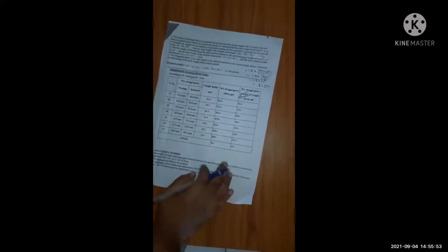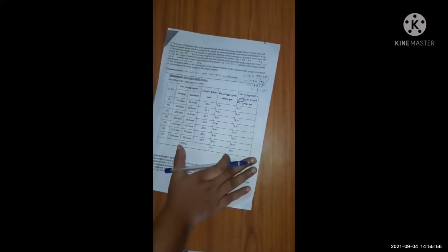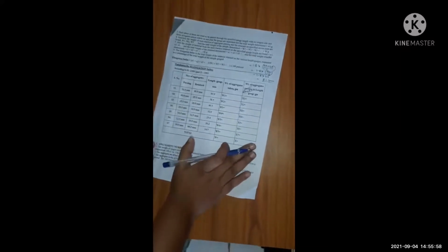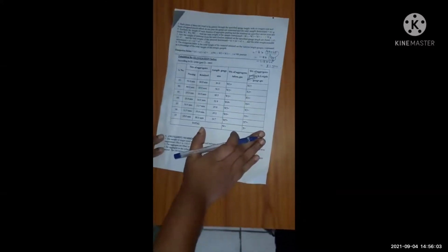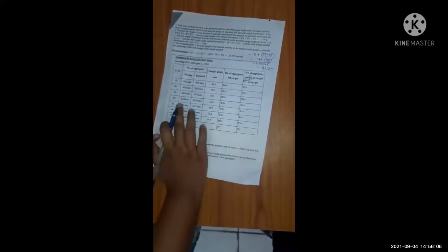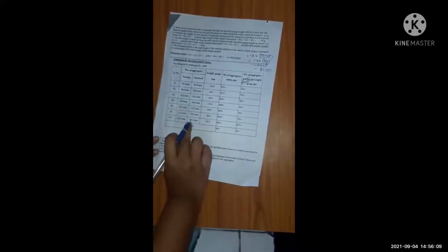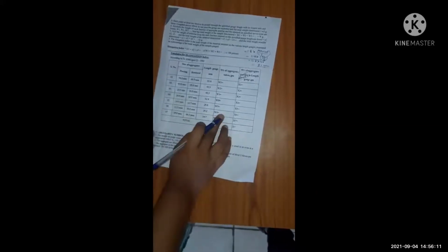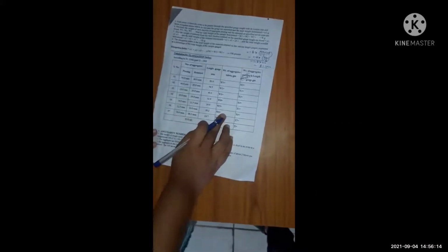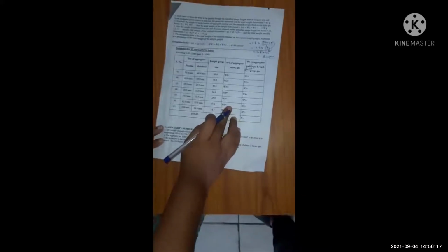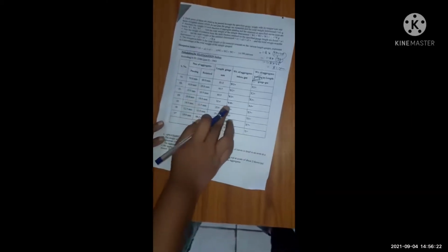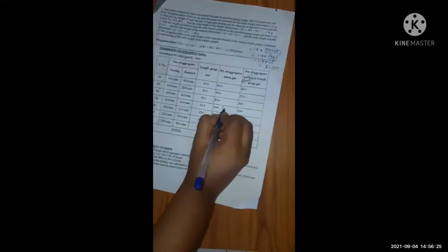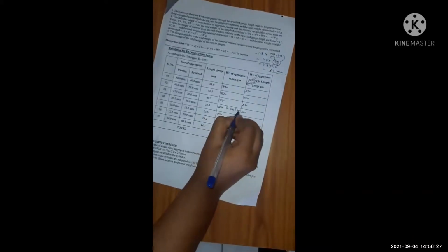Now comes the calculation portion. Now we see the table. This is our table. We started with 20 mm aggregate of sample in this test. So we use sieves starting from 20 mm to 6.3 mm. We have taken in our experiment different gauge ranges. In the 20 mm to 16 mm range, we found the weight 2.065 kg.